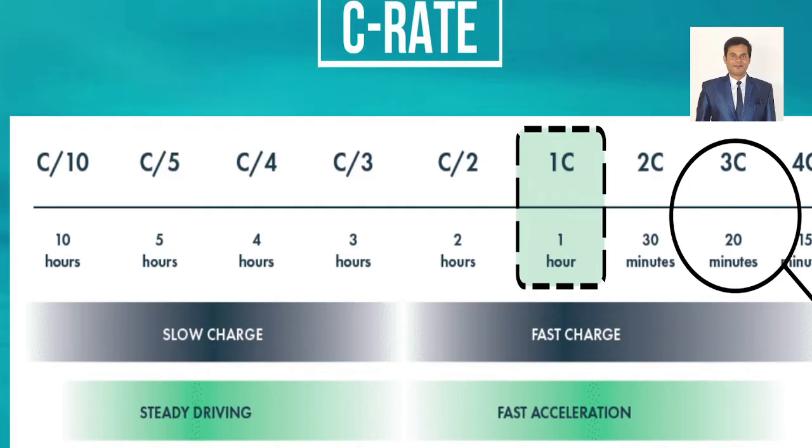So this is where we have to focus more on battery life and temperature, right? Temperature is a major factor. Please focus on the temperature and try to monitor it, so that the battery life can be improved. If you increase the temperature suddenly, there is a drop in charging and discharging, and the battery life will also degrade very soon. The battery can last as long as possible. So please look after the battery conditions and the C rate also.